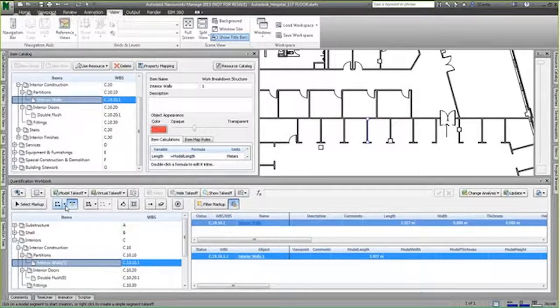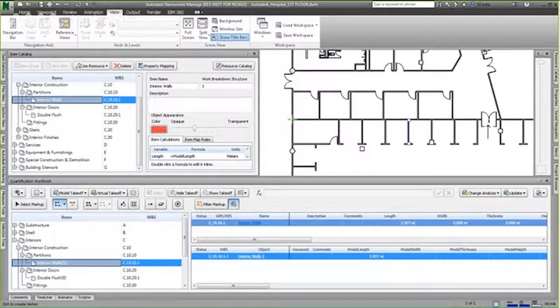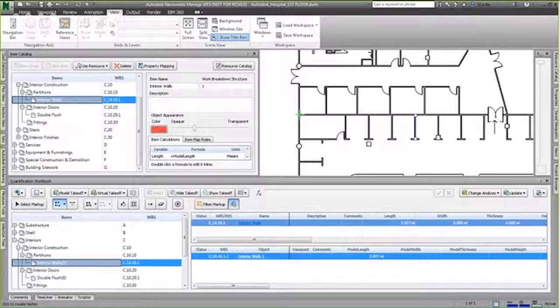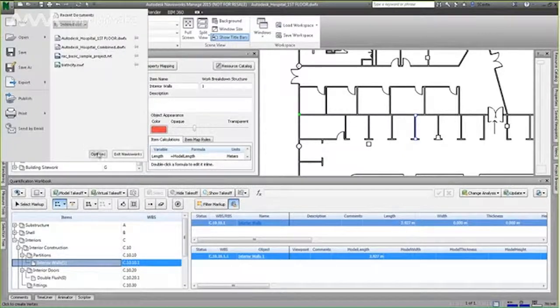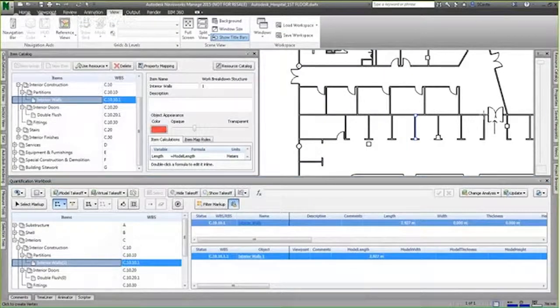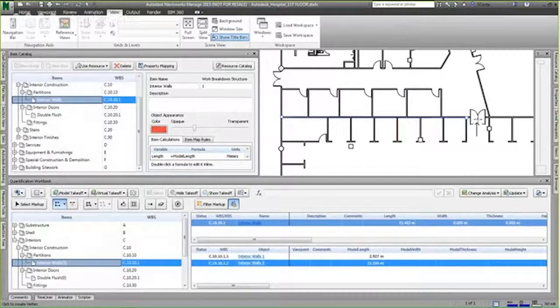So if you wanted to do a long polyline, for example, you can select polyline, and what you would normally be seeing is that green tick. The only reason you can see it is because I've done this little pan. Unfortunately, this is where my graphic card is misbehaving, but if I start off there and I have my object snaps turned on, and I would invite you to do the same, go to your options and enable snapping. You may want to do snap to vertex, snap to line vertex, maybe not so much snap to edge for this particular type of work. Then you can just snap, and with a right click, I've taken off that entire length right there.